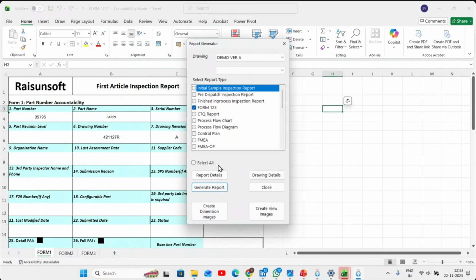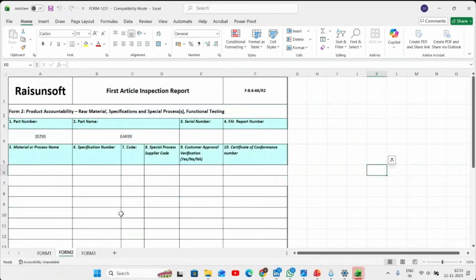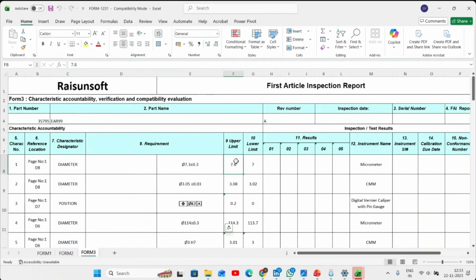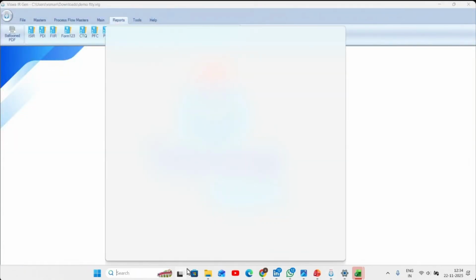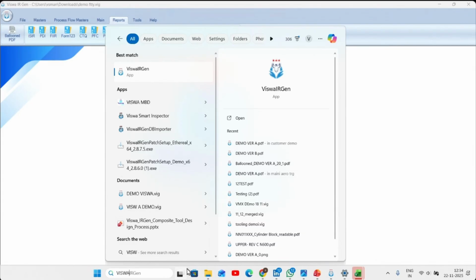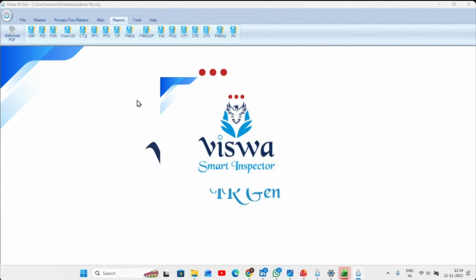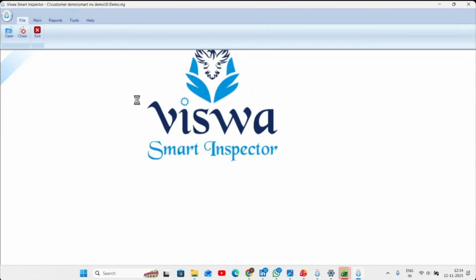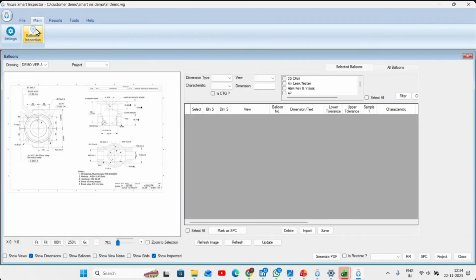Are you purely in aerospace, sir? Yes, sir, purely in aerospace. AS standard you follow, AS certificate holder, sir. Oh, nice. So we can make Form 3 into a report format, sir. Most importantly, after you make the part, you want to inspect the observed values, right? Normally, the CMM guys are under complete pressure to fill the Form 3. Let's say you have 300 parameters and you are producing 6 or 8 components. Your CMM guy has to fill all the Form 3 completely, correct?